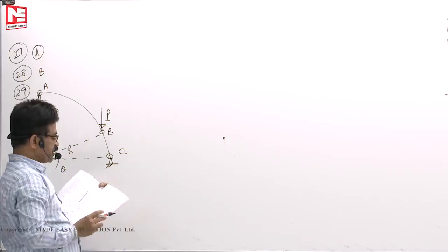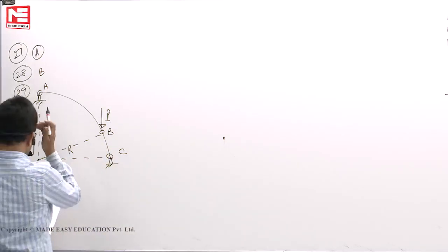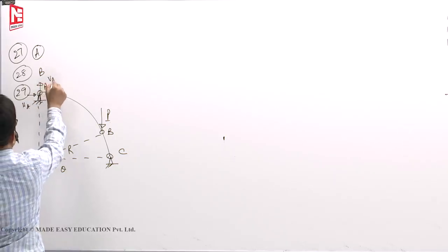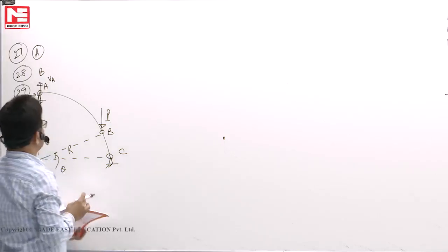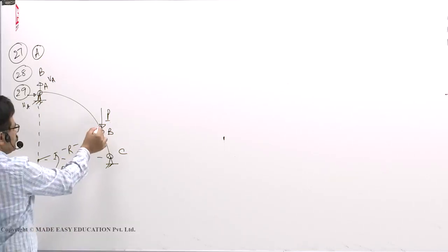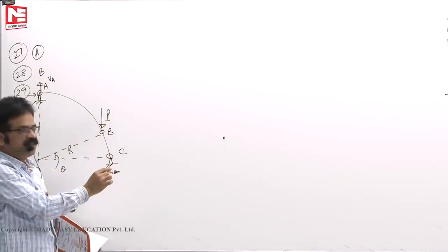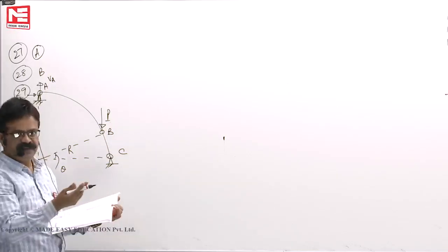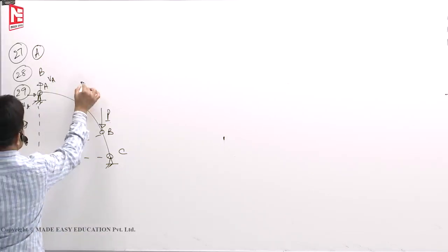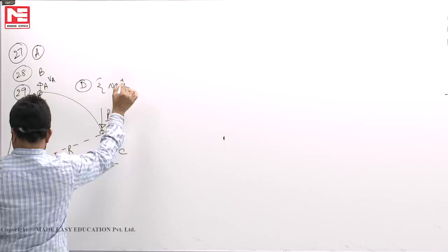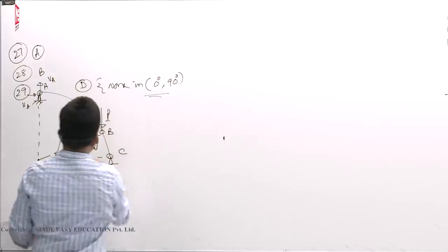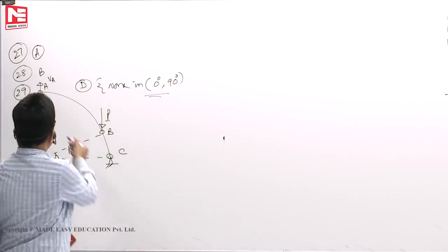Shown in figure is a quarter of a circle. The vertical load and horizontal components of the reaction at A are equal. HA, VA are equal. The value of theta. If VA and HA are to be equal, then theta will not be in this range. When you calculate it, you will get absurd values, negative values for theta. So none, theta not between 0 degrees and 90 degrees, because you will get theta value beyond this range when you are calculating.